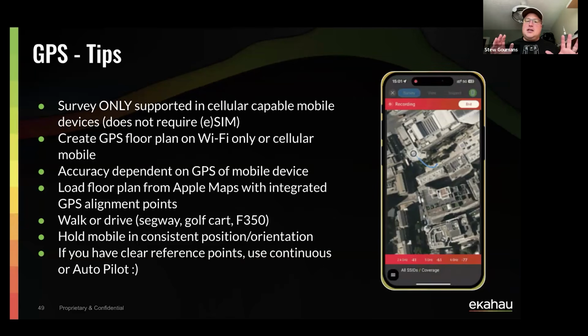As soon as I turn on the GPS and before I start the survey, as Troy was mentioning, let that blue dot settle in to where you are and then start going, because it needs to make sure that it knows where you are, and then hit start the survey. That'll help guide you a little bit better. And sometimes if the map is a little bit tilted, if you are going to use that tilt like a map, you want to make sure that it's flat down, because sometimes it may not understand the elevation change and whatnot. So you have to take that into consideration.